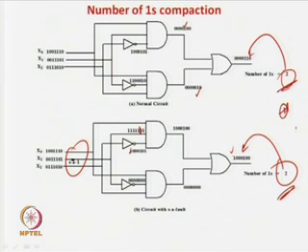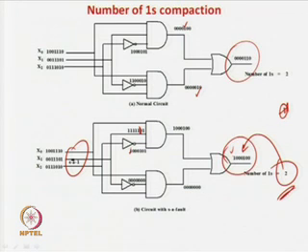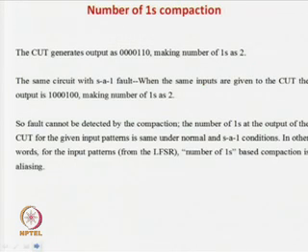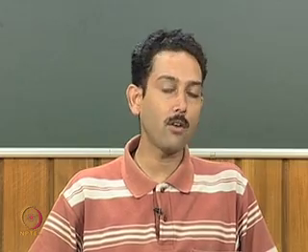So, in this case 10 you can store in the ROM, that corresponds to the value of 2, and you need not store this long flat value. Okay. So, that is the idea. The long value is not required to be stored, so you save a lot of memory in the RAM. So, the RAM size is less, but what you have to pay is that for some of the fault cases there can be aliasing as in the last case. Okay. So, that is what is being told over here.